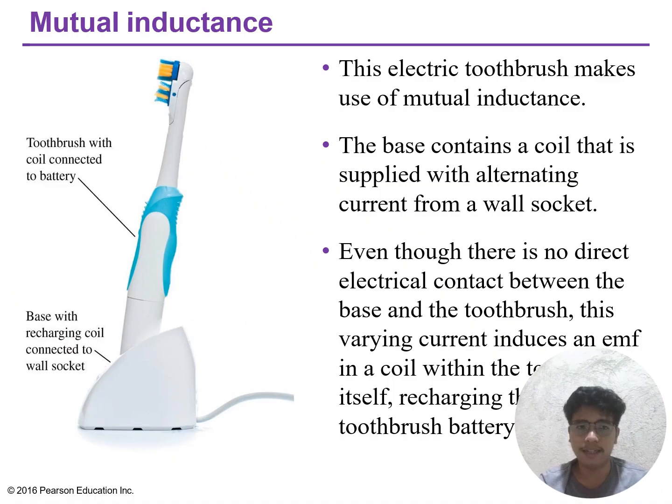This system is elegant because there is no danger of electrical shock, unlike a direct electrical connection. There are no moving contacts to wear out, and the charging is broken when the toothbrush is removed. The mutual inductance drops to zero when the coils are far apart.